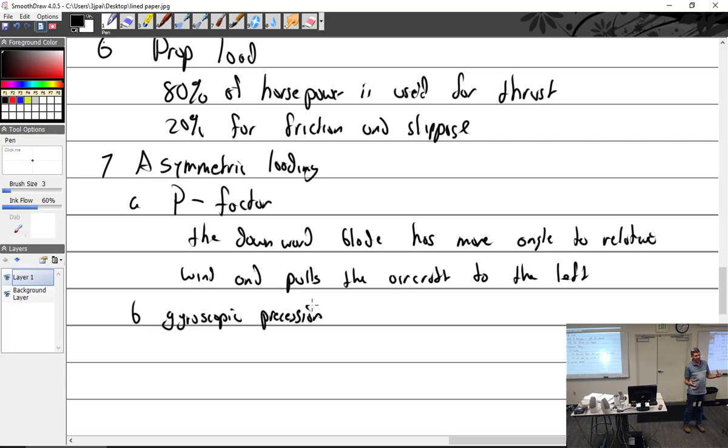I didn't think I'd be talking about this. I usually bring a little bicycle wheel and I could show you, but Phil will really cover it in great detail. So in a tail-wheeled aircraft, think about it, we're sitting back this way, and so the propeller disc is kind of slanted this way. Everybody see what I'm talking about? Slanted this way. Well, and it's spinning this way. Follow. Okay, follow. Spinning this way. When I raise the tail up, it's like I pushed right here.